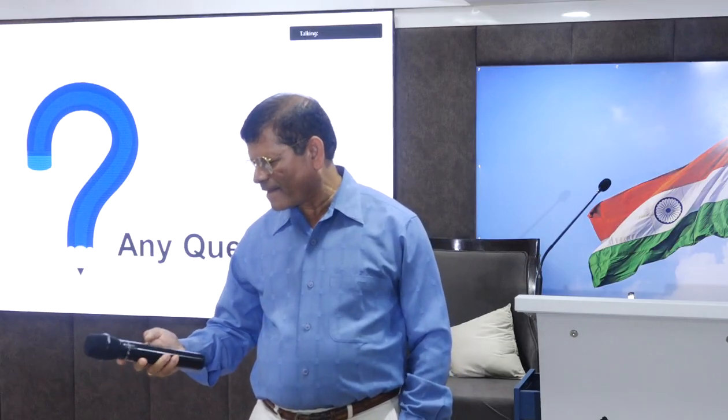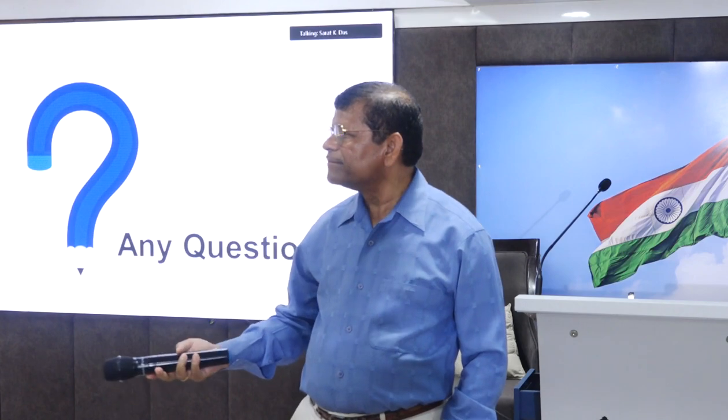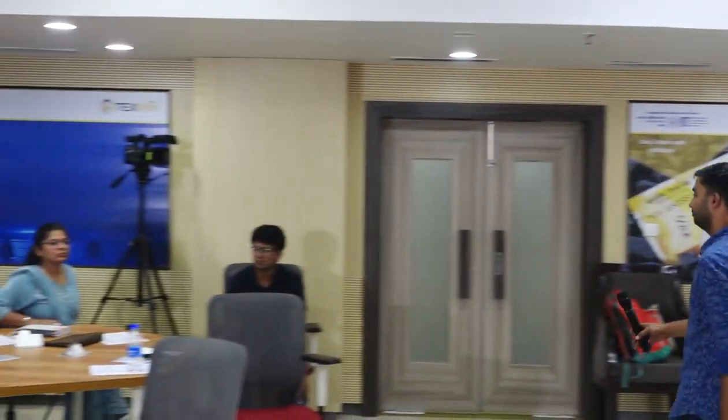I think their concern may be for the slope stability. Yes, so we are using c and phi. For a conservative point of view, generally when we are determining c and phi, we consider the peak stress, because we get it from the stress-strain curve. On that curve there are two points, one is the peak stress, another is the residual stress. If you get the c and phi corresponding to the residual stress, and you do the design for that condition, you will be on the safer side.